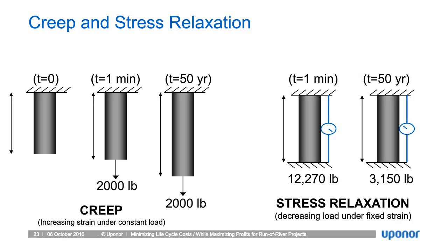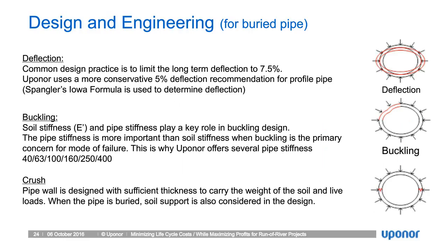And this is an important aspect if we do bury the material, and let's say some of the bedding is trying to push into the pipe, it will respond and the pipe will relax. If we have a material such as a rigid pipe that does not relax, and you have the constant stresses, the constant stress can result in a rupture of the pipe. So this creep and stress relaxation is to highlight that the material can adapt to its environment and reduce the stresses applied to it over time. That's a unique characteristic of the HDPE.